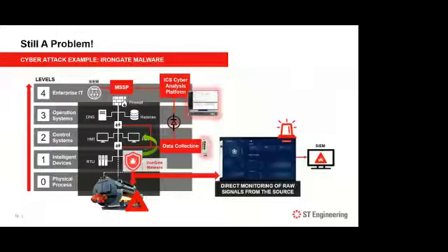This is where we think that level 0 monitoring will be required. Here, when we talk about level 0 monitoring, essentially we are talking about the electrical parameters, such as voltage and current. A component, or rather a sensor, will be placed in between level 0 and 1 to monitor the behavior of the voltage or current, and thereafter flag out the anomaly. Take for example, during the learning phase, there will be a minimum and maximum threshold being set, in which suddenly due to cyber activities, it exceeds the minimum or maximum threshold. This is where the alert will flag out.